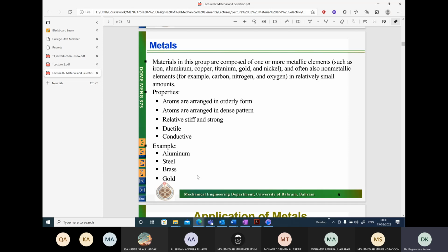When I say structure, I'm talking about the face centered cubic structure, BCC structure, etc. They occupy certain positions, and these positions could replace existing atoms. For example, in gold, they could replace existing positions, and in the case of steel, carbon atoms occupy certain interstitial positions. Okay, so this way they create a solid solution.